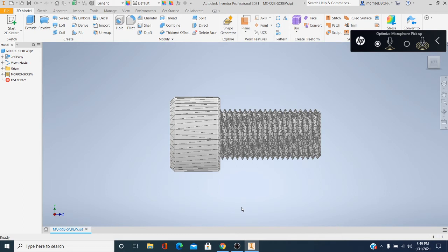And what you have to do, though, is save it as an IGES file. Sometimes it's just IGS, so you may see it either way. So save it as an IGS file, okay? And save it to your directory that you're familiar with, all right? And then you can close out the McMaster-Carr catalog, and then you can go open up Inventor.